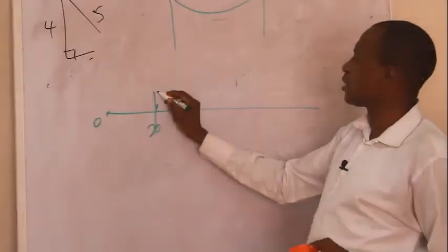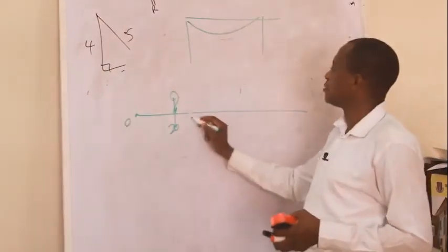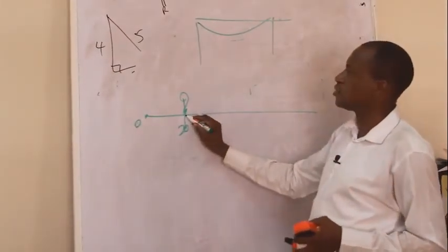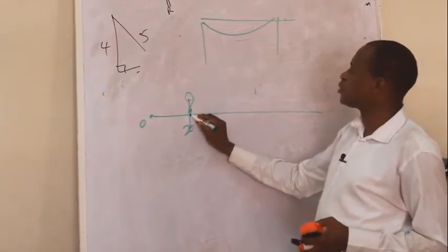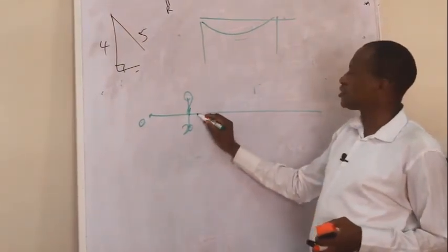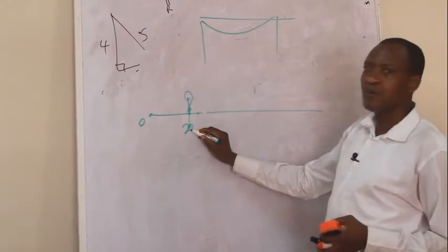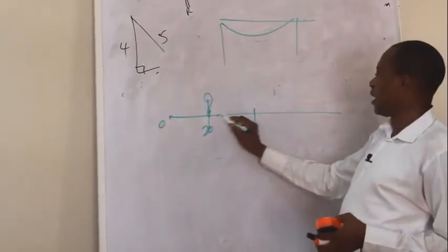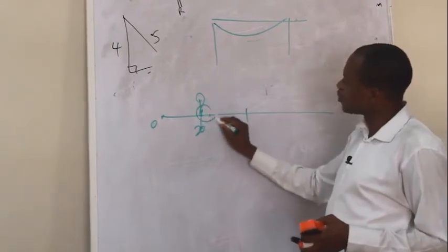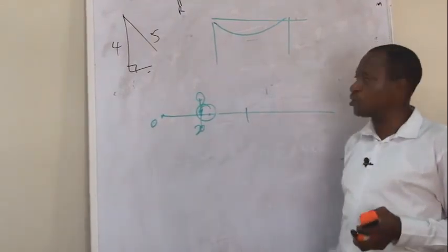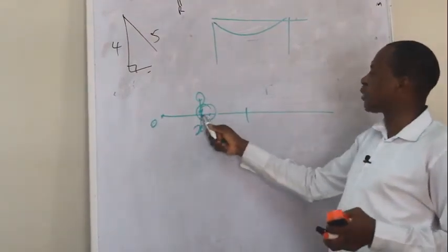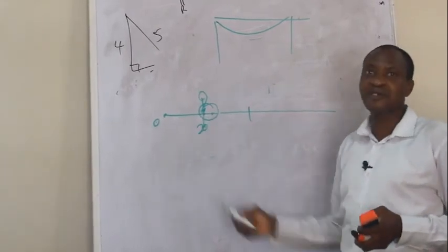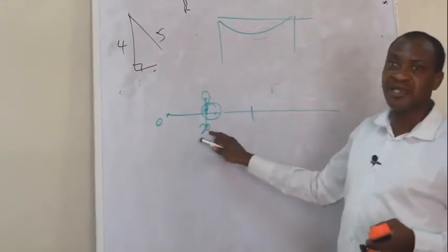You put an arrow here, this person moves to this place, and instead of putting it exactly here, the person puts it here. But the other person has taken the tape to this point and measures another 20 meters. What happened to this place? The person who came from here did not look at this point very well. He did not know exactly where this person left.